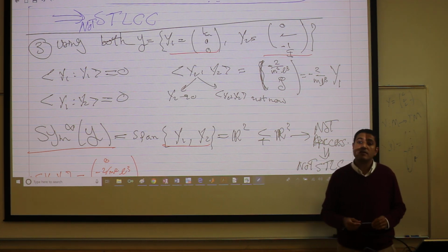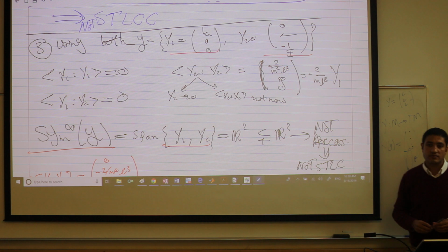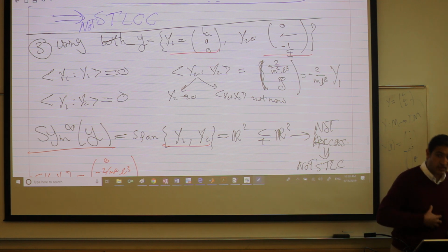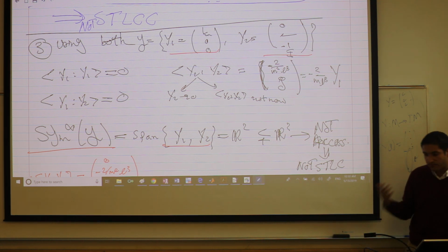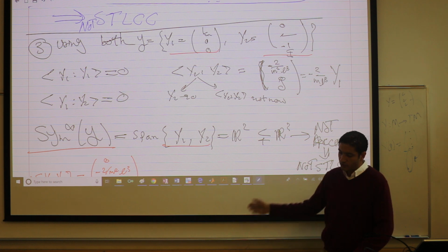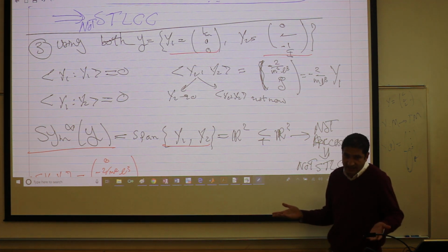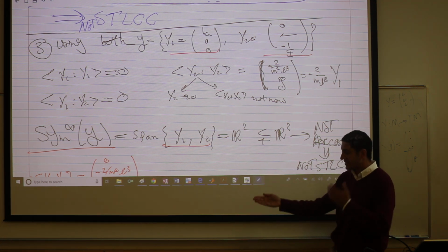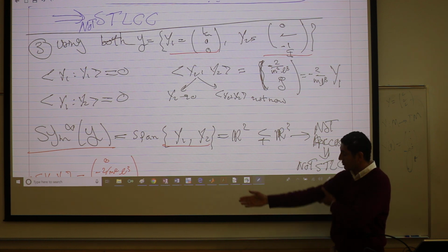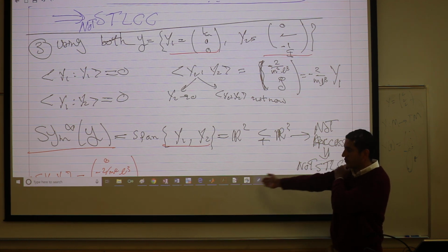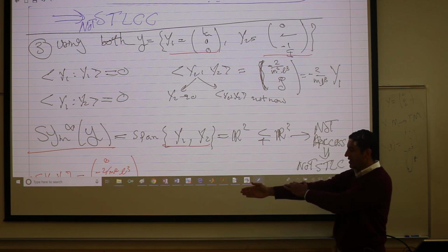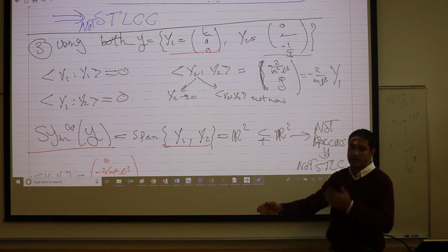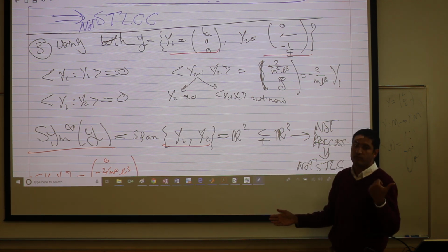That's what I'm asking. So it will always be that case? No. Because sometimes the drift gives you the ability; the interaction between your forcing and the system dynamics sometimes gives you action. In flapping flight, for example, it has to abide by the physics at the end of the day. When you do this back and forth, this is indeed a symmetric product. The result is the symmetric product of the control torque. You have a control torque input for this guy affecting the state space of that guy and the state space of the body. The interaction of this motion with the drift of the body. What's the drift of the body coming from? From aerodynamic forces.